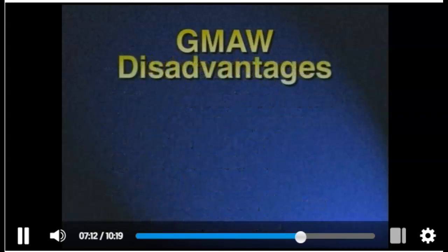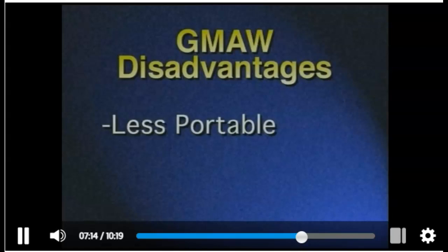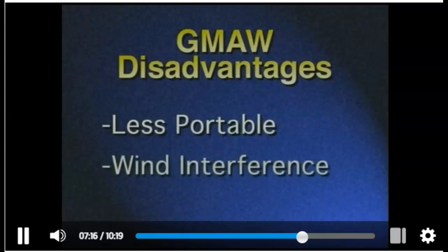There are some disadvantages too. GMAW is less portable, and breezes can blow the shielding gas away from the puddle, which makes it unsuitable for outdoor use without protection from the wind.